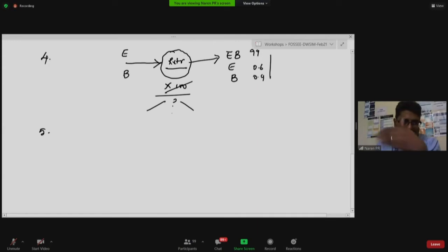My idea of this 10-20 minutes is to give a holistic view of how you can use DWSIM to learn your concepts and at the same time apply your concepts to build a flowsheet that you want, that is, construct a digital process plant, as I said yesterday. One is the rate-based information that we have, and another is equilibrium-based information. Both of these can give some idea of this realistic conversion.